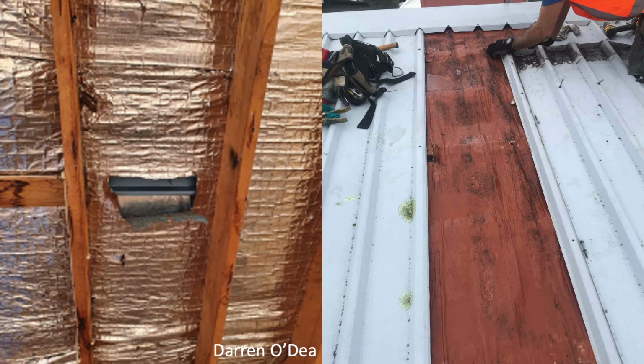We're also seeing patches of mold there, again, very far from ideal, because while that mold is in the roof, once it dries out and the mold spores become mobile, they will be able to find their way into the conditioned space. Not to mention the degradation that all that's going to have on not just the craft paper there, but also the other materials and products in that roof assembly.